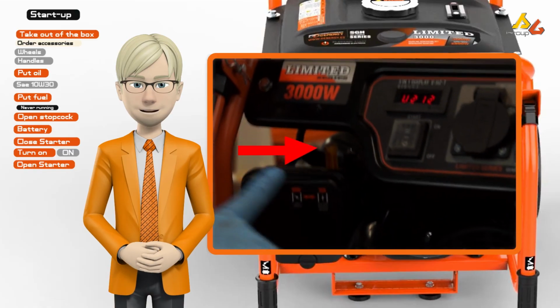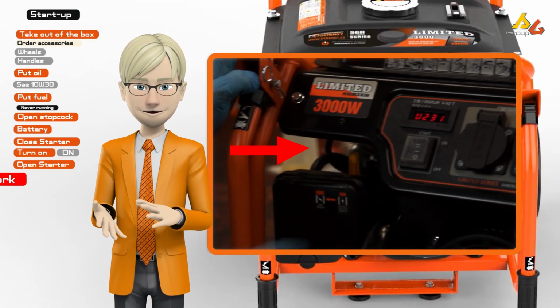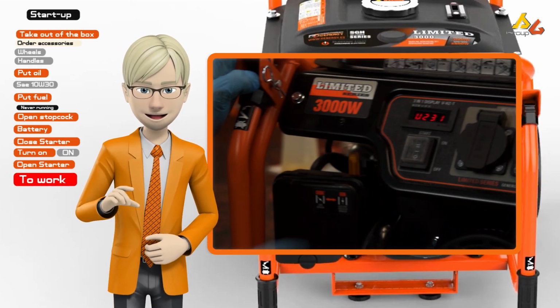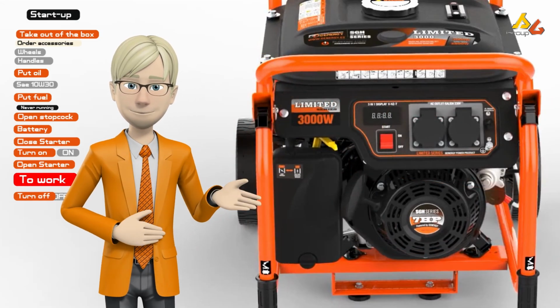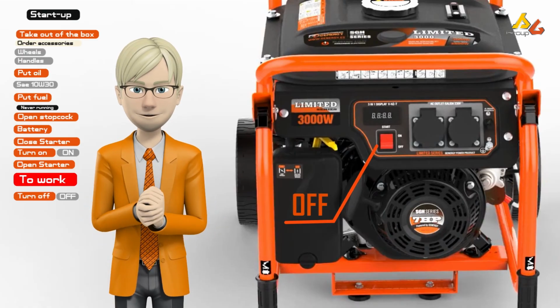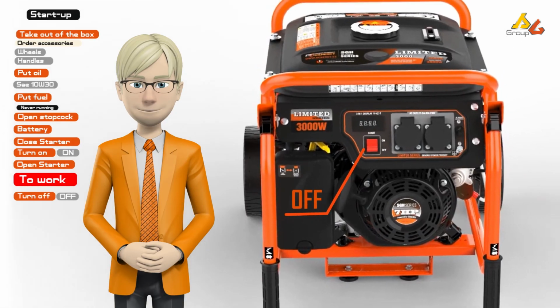When we've finished, we turn off the generator simply by turning the main switch to the off position. And we must remember that both at the startup and shutdown phases, there should be no appliances connected to the generator. If you have any doubts or problems during the starting of your generator, please contact our customer service team and we'll be happy to help you.